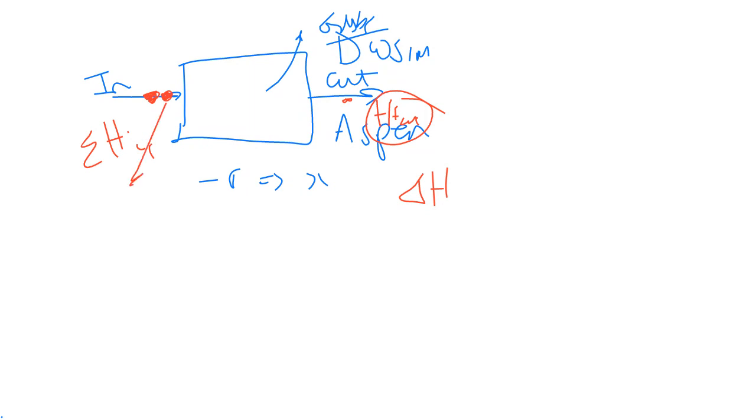Let's say you've got A plus B that's going to be converted to C. It's going to ask, what is my state at the inlet? What's the temperature? What's the pressure? And therefore, what's the enthalpy of A at that point? What's the molar flow rate of A? Then it can read it up from tables and from all its databases, and calculate the enthalpy of the inlet flowing stream.